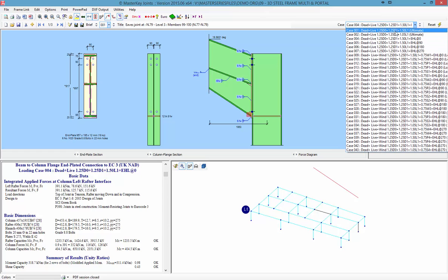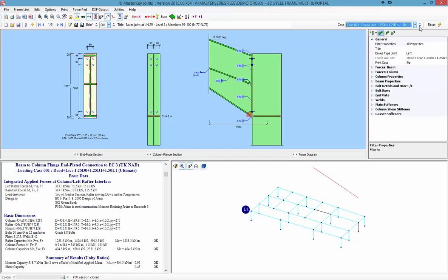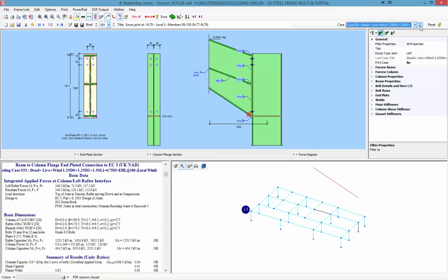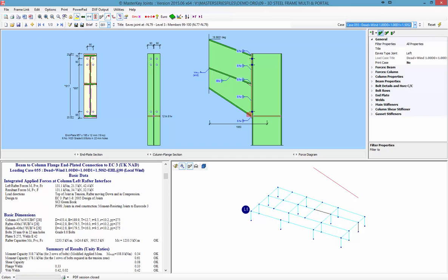You will see that hopefully this one is set to no because the notional horizontal force, case 4 is more critical. And I assume I have a reversal case. Maybe I don't. That's giving me a negative moment. There we go. Case 47 is the most critical in reversal with dead plus wind. So yes, it will select the cases for you after an auto design.